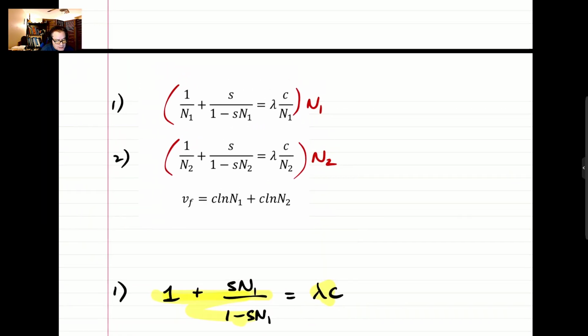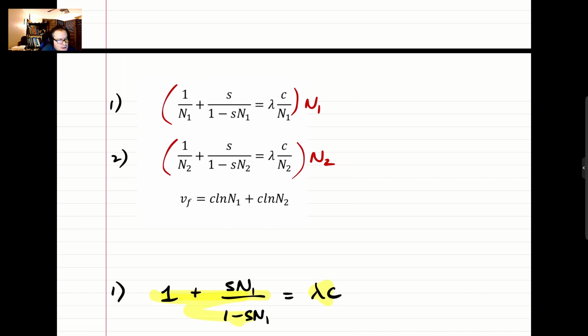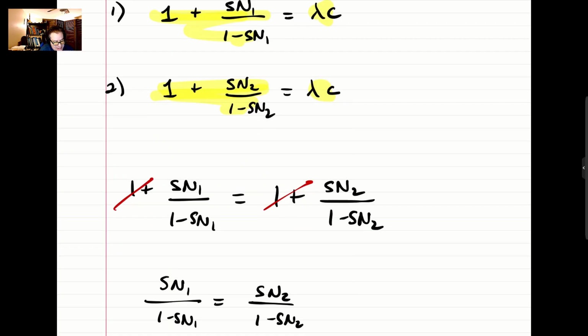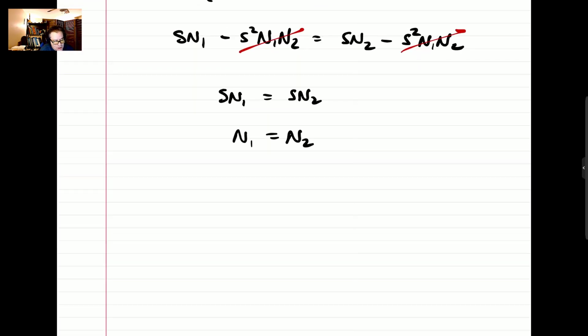If all of these are simultaneously true, which they must be for the solution to the system of equations for the minimum of the objective function by the method of Lagrange multipliers, we need the solution of this system. And in the solution of that system, we've been led to the conclusion that the n1 and n2 values have to be the same. If you remember, they're the mass ratios in each stage burn. So the mass ratios are the same, even though the individual masses don't have to be the same. We'll see that in a moment.